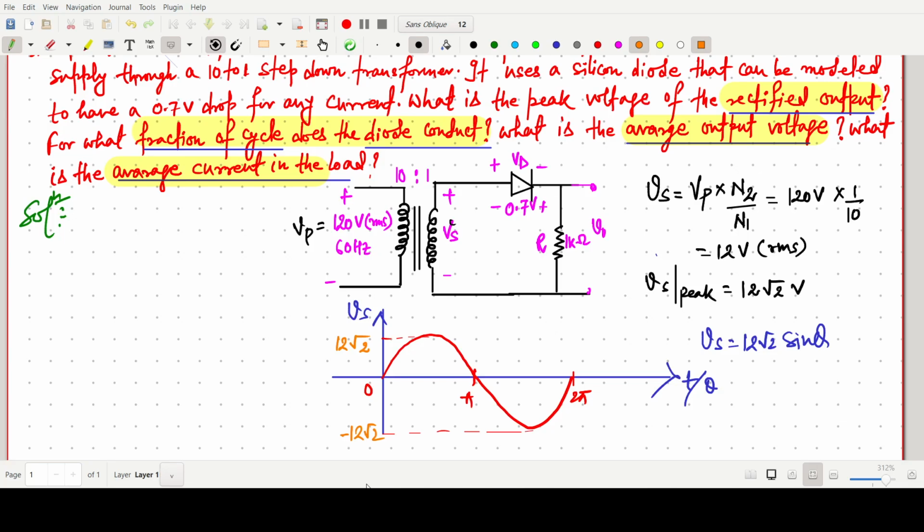Before that, in our earlier video also we have covered that this diode has a voltage drop, a constant voltage drop of 0.7 volt. So we have to find the transition voltage. There is a concept of transition voltage. Every time, in the case of a rectifier and also in a clipper circuit, we find this transition voltage to identify the reference line, after which the diode conducts. This is where the diode is just on and the current in the circuit is 0.